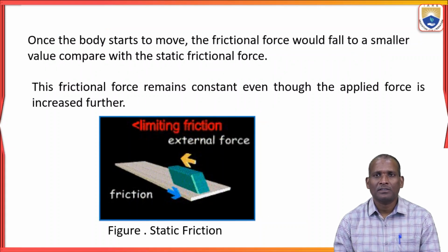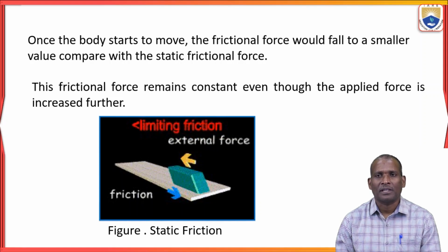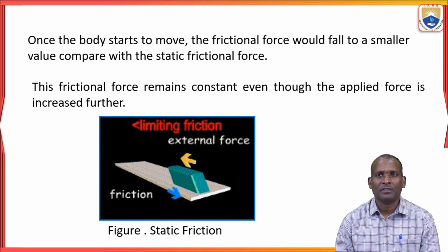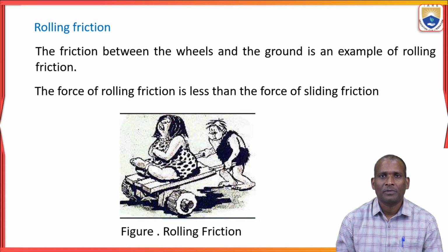Once the body starts to move, the frictional force falls to a smaller value when compared to the static frictional force. This frictional force remains constant even though the applied force is increased further. The frictional force remains constant if you keep on increasing the applied force. Next one is rolling friction.